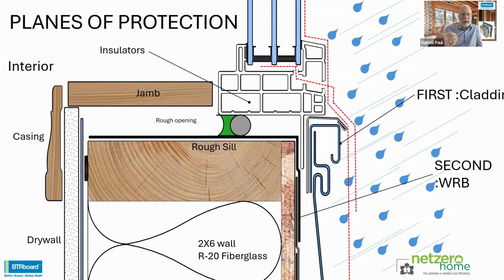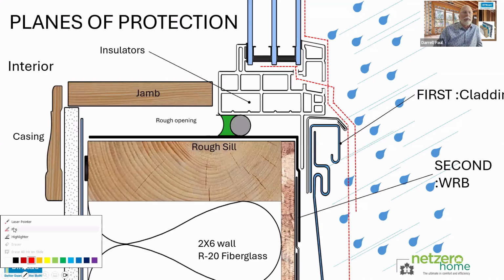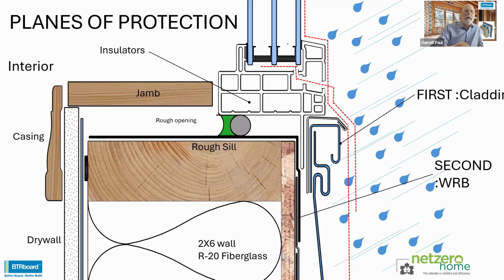Then the second line that you see that goes underneath the two glazing stops there in the triple glazed window, the three panes of glass, you can see there. You've got window glazing. Here's my pen. Found it. Right up here. You've got windows that have glazing, but the water can actually get in and around the glazing. And the reason for that is when the wind blows and the glass deflects, you have these rubber seals here that could possibly open up and let water in.